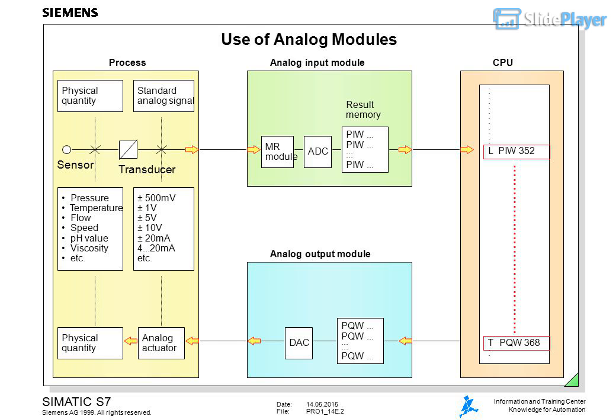Sensor: measuring sensors respond to changes in the quantity to be measured by linear expansion, angular deflection, alteration of electrical conductivity, etc. Transducer: measuring transducers convert these above-mentioned changes into standard analog signals, such as plus minus 500 millivolts, plus minus 10 volts, plus minus 20 milliamperes, 4 to 20 milliamperes. These signals are supplied to the analog input modules.